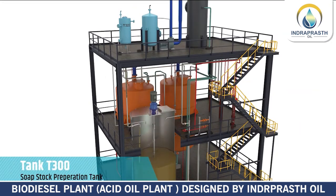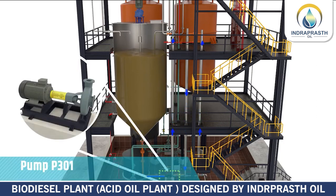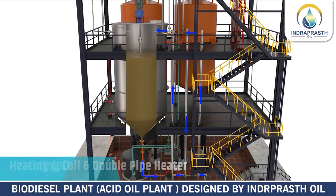The soap stock from the alkali neutralization plant is taken to the preparation tank T300, where a calculated amount of caustic lye from the overhead tank T322 is added to saponify the residual phosphatides. This mixture is then homogenized by the agitator, and this mass is recirculated to the tank by a pump P301. The temperature of the mixture is kept at 80 to 90 degrees Celsius by the heating coil in the tank and double pipe heater E302 in the recirculation circuit.